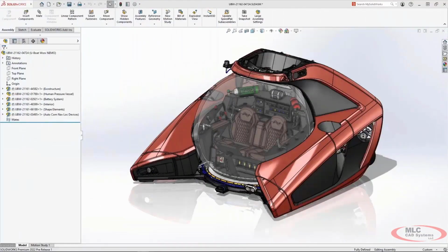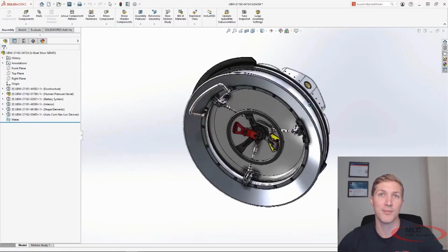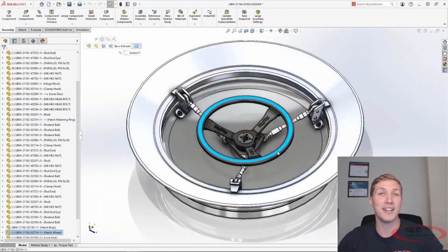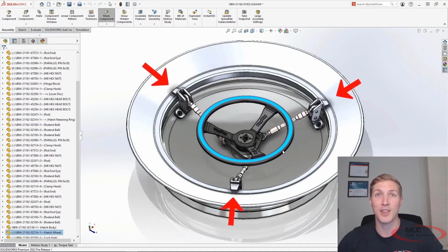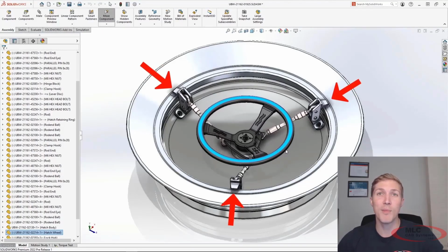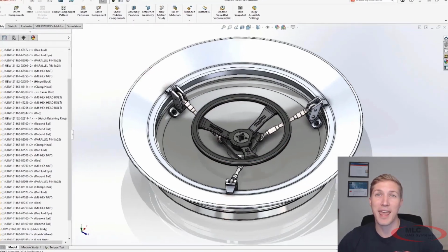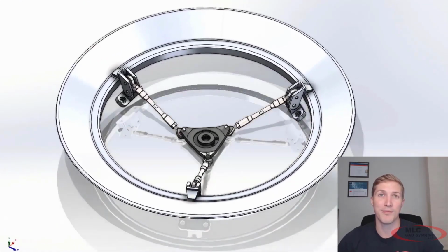The submarine also utilizes a more complex hand wheel design to close the hatch before diving. In order to seal properly, at least 500 newtons of contact force is needed between the latch fingers and the retaining ring. That's about 112 pounds in freedom units, so I want to make sure the hatch design provides enough mechanical advantage that it can be sealed easily by your average submariner.